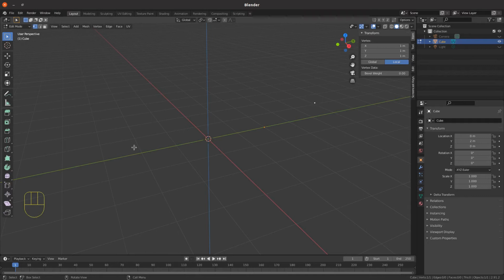that vertex, and we've got in the tools menu a lot more tools lined up, and the editing tools are down on the left hand side, but the shortcut for extrude is simply to press E. So while there's a vertex selected, if you press E and then go Y -2 and enter, you'll see that the selected vertex has now been deselected, and a new vertex has been extruded out to 2 meters on the negative y-axis.